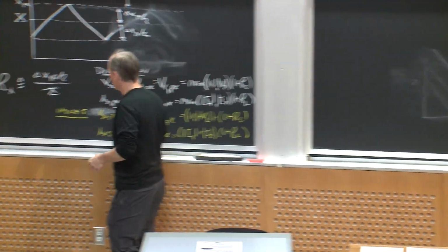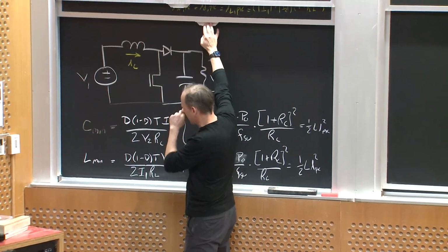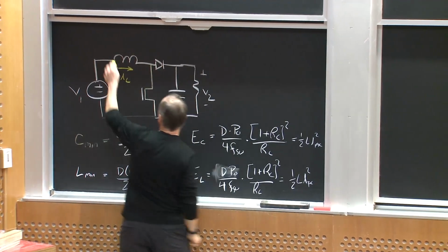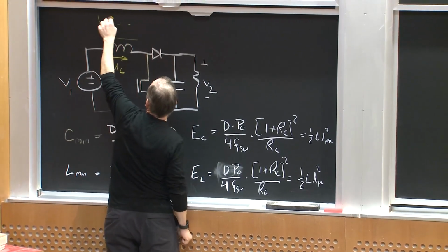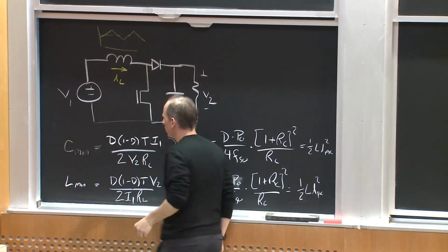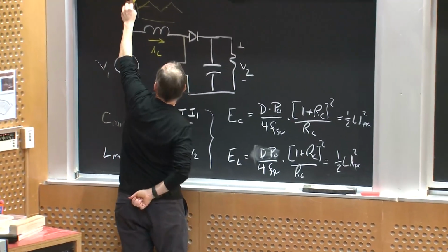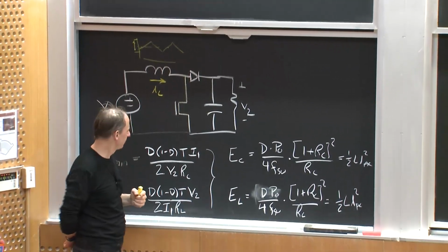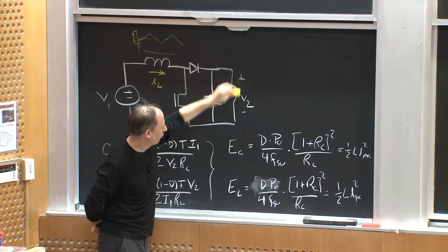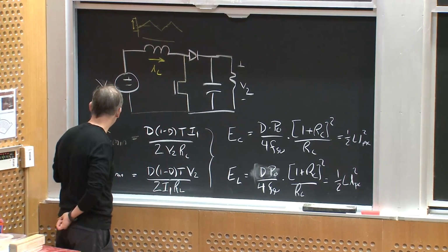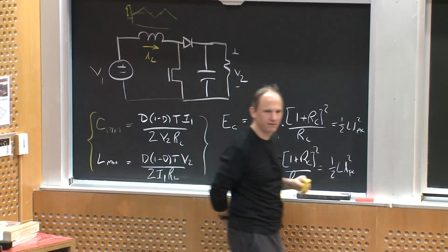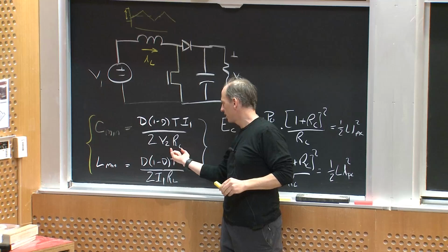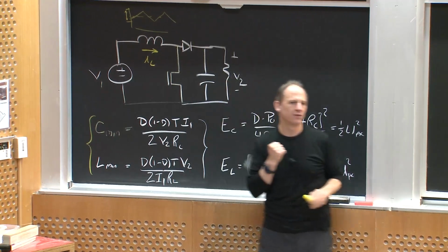The other thing we did was we took that and said, okay, I know that my inductor current, for example, has some triangular ripple on it, right? So this IL looks like some average value and some ripple, right? And we could calculate, if I wanted to limit my peak-to-peak inductor current ripple below some value, because that's my input ripple current, or my peak-to-peak output voltage ripple below a certain value, I can come up with minimum capacitor and inductor values to do that, which are related to the conversion ratio. And I expressed it here in terms of the allowed ripple ratio of the designs.